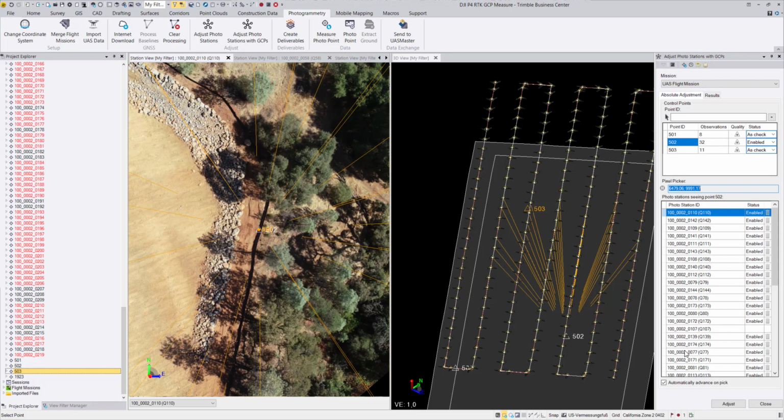And also what is now possible, because we have a control point, we can also apply a shift correction. We can shift the GNSS accordingly, fitting if there's a systematic shift possible to apply it to this ground control point. And therefore then hopefully we will see that our checkpoints will also fit much better into this adjustment, and we will then have only small residuals in these checkpoints.